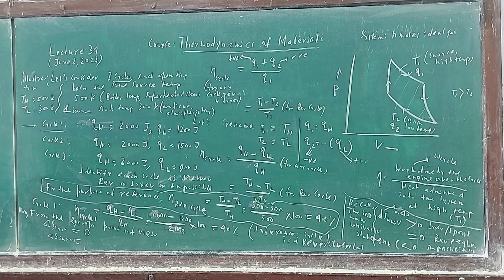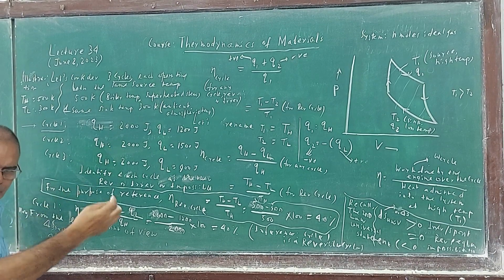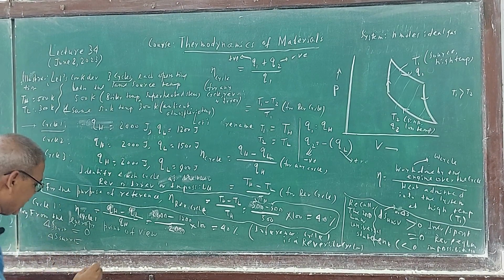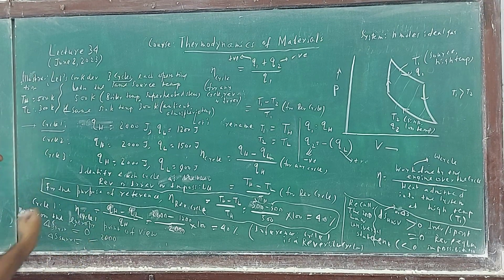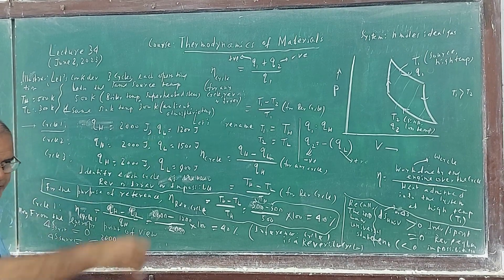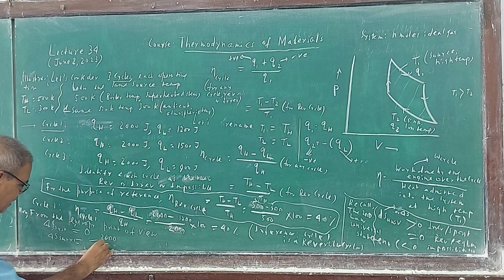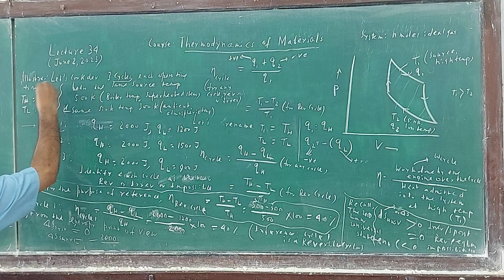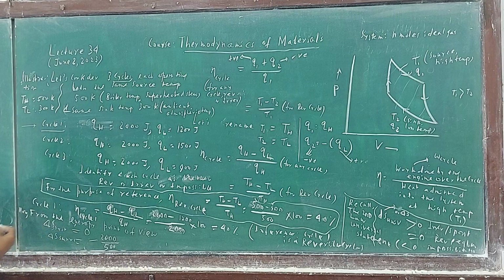Be clever, be smart, take advantage of state properties. Delta surrounding: the QH of 2000 is absorbed, so the surrounding loses the opposite sign. So minus 2000 on the source side; the boiler is losing that heat. Minus 2000 divided by the boiler temperature, which is 500.